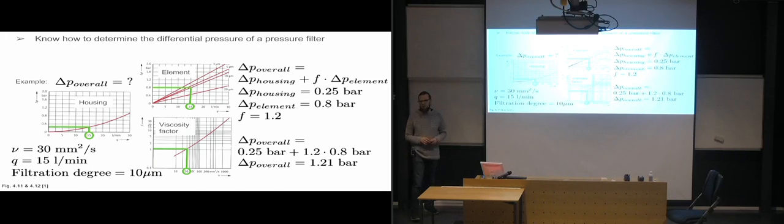That's the main reason why you should change the oil filter on your car every time you change the oil, because the filter has started getting very dirty, so you get less flow going through it. So it's the same for hydraulic systems. You want to change the filter at regular intervals to make sure that you have a good enough flow through it.